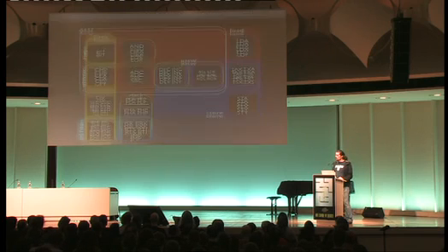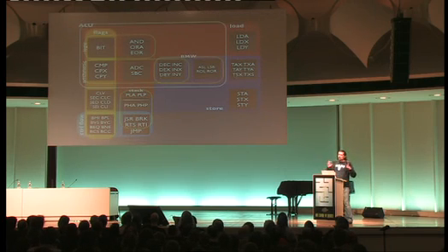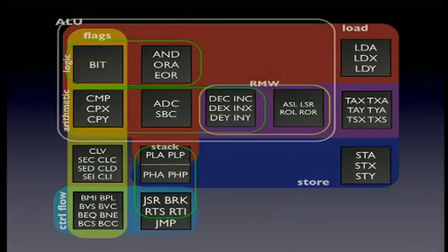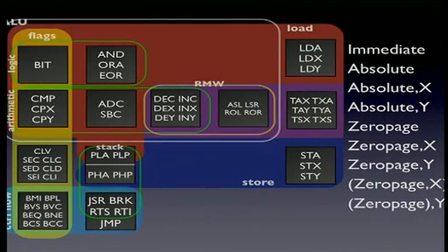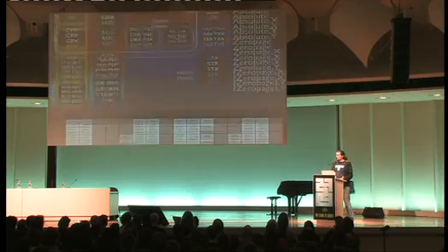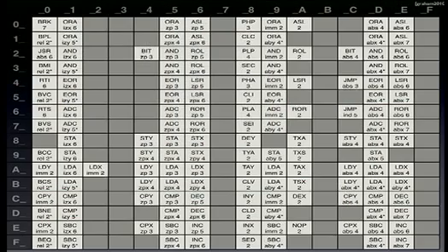That's an interesting thing. So looking at all the instructions that we have and looking at all the addressing modes that we have, if we combine them, if the CPU were completely orthogonal, being able to combine every general purpose operation with every addressing mode, it wouldn't fit into the 256 different opcodes. So what they did with the opcodes is only encode the ones which really make sense, the ones which are most interesting and most important. So only about 60% of the opcode space is used. And the rest is just, well, they say it's undefined.